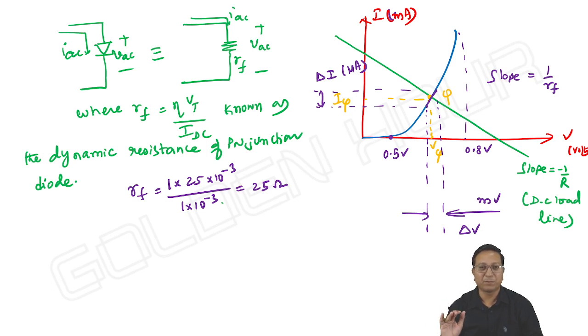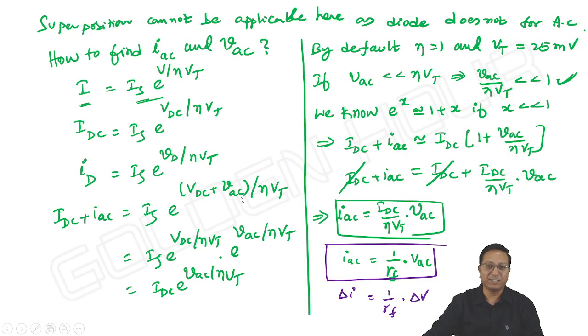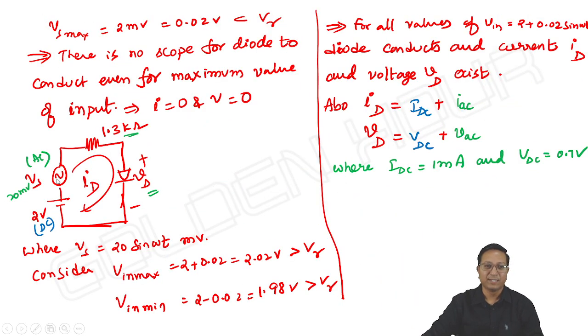So by giving a proper voltage supply to the diode circuit, we are obtaining the operating point. Next, after setting the operating point, we are applying AC along with sufficient DC. It's 2 volts DC, not 0.5 volts or 1 volt DC. We are giving an appreciably good value of DC, so that for all values of input, a combination of DC and AC, the diode is in conduction.